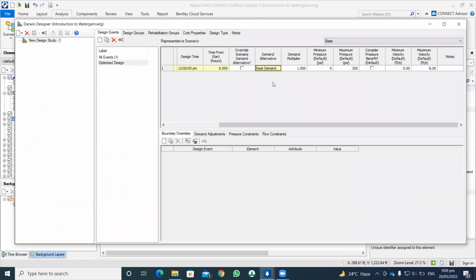Most of the time when you design a water supply network, we design for a peak month of the year, the peak week of the month, the peak day of the week, and for that peak day we basically design for the peak hour. How we will incorporate these peak months, weeks, days, and hours, I will discuss in a separate lecture when I start the case study.